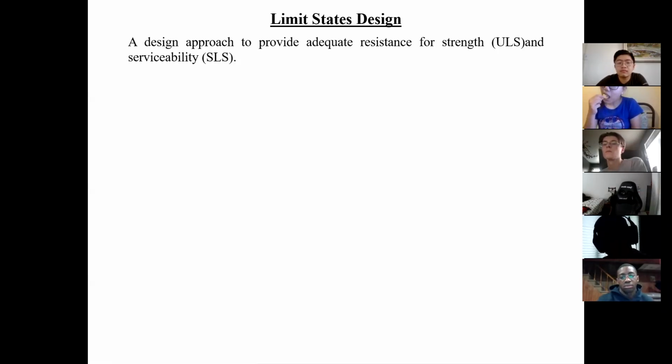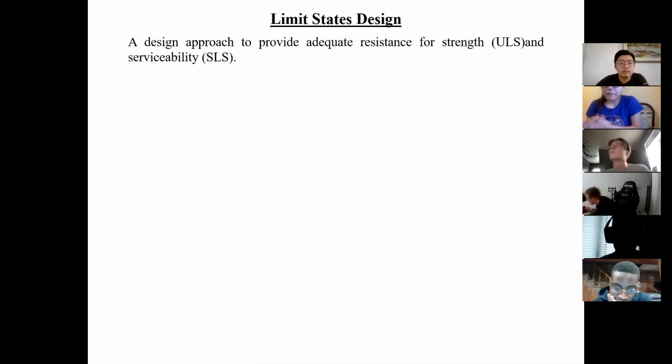The only thing I haven't done is I haven't included vibrations in serviceability, and I'll tell you why. Depending on the spans that you guys are working with, sometimes vibration is not an issue, especially if you keep the deflections within what we call acceptable deflection. That also tends to control the vibration. So we'll talk about that more in due course.